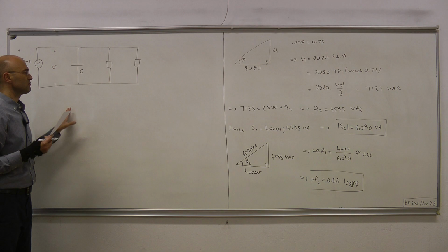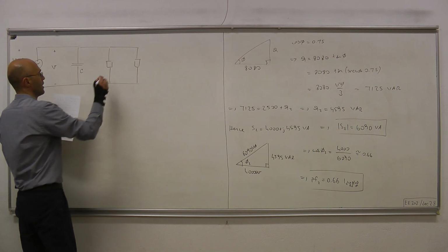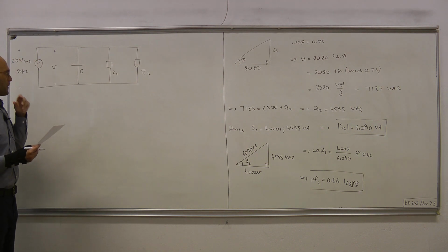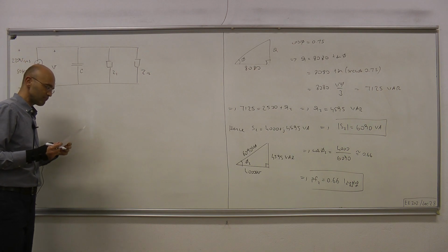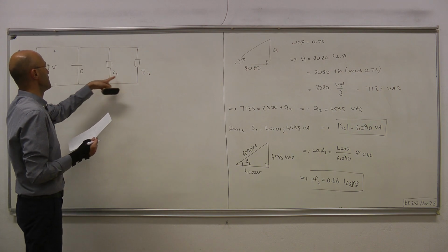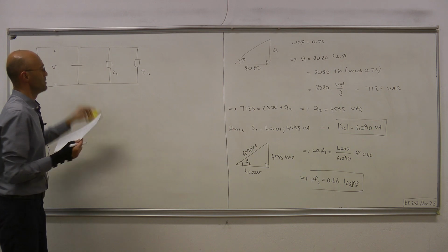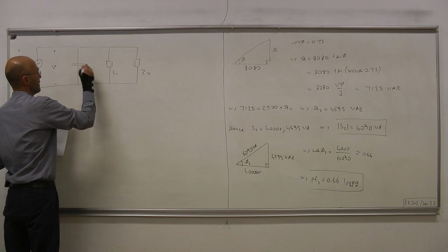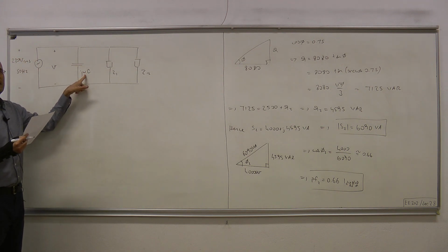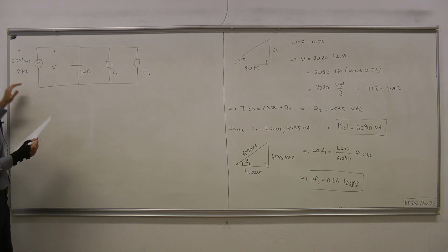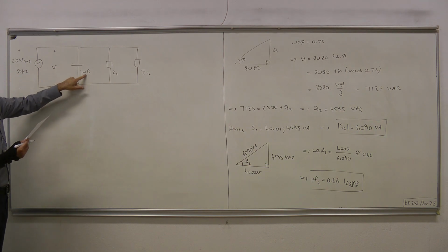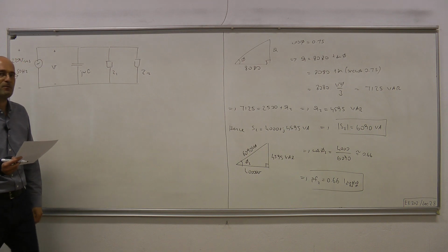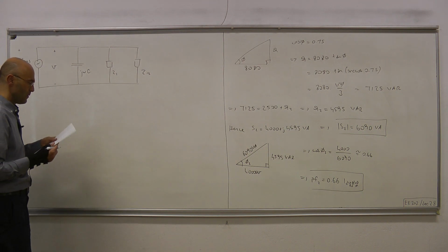This is the capacitor, and here we have Z1 and Z2. Well, these are impedances. Therefore, to be more grammatically correct, let's write this also as impedance 1 over j omega C, and this omega is the frequency of operation in radians per second, and we're given the frequency in Hertz. Therefore, omega in our case is this times 2 pi, which is 100 pi radians per second.